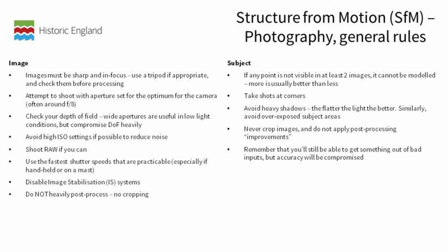I sort of mentioned this earlier, but definitely any point you want to measure has to be in 2 photos, preferably a lot more, maybe up to 10. I touched on this earlier as well. If you want to get a continuous model around your war memorial, then you need to be taking photos opposite the corners, so you've got something bridging the gap between the faces.